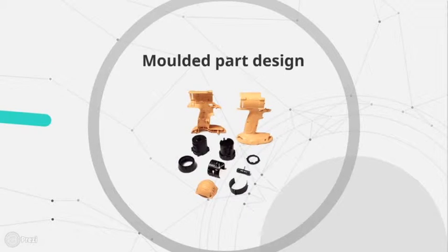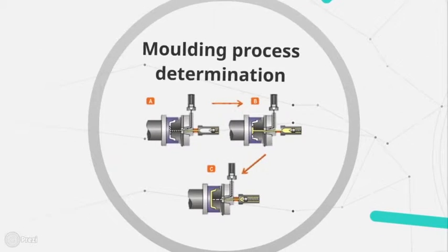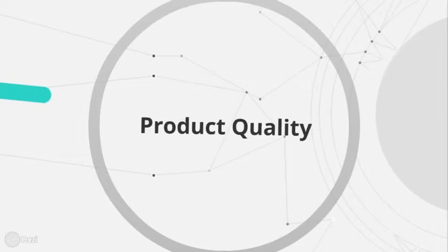So using computer-aided design, we can design the part that is going to be molded first. And we can take the design to a software such as Mold Flow or internal features within Creo Parametric to design the optimal mold that we're going to use to mold this product in real life. And we do that by determining molding processes and also the parameters such as the position of the gates, runners, the injection velocity, and also injection temperature, which are very important parameters in the actual molding process.